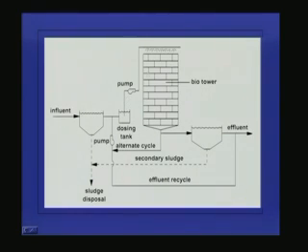So the treated water is collected here, it is going to the secondary clarifier and effluent is going out after the treatment. So we can have the recycling either from here, so we can see the effluent recycling, and here whatever is the sludge in the secondary clarifier, that is collected along with the sludge from the primary clarifier and it is going for further treatment.